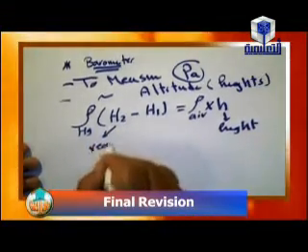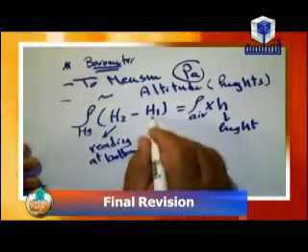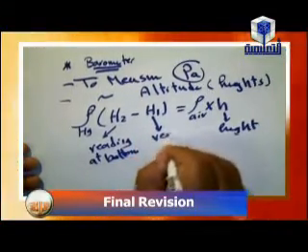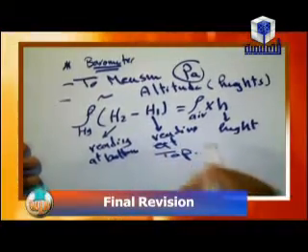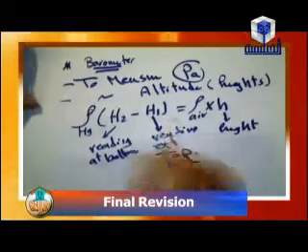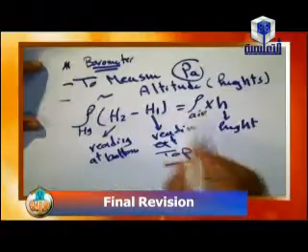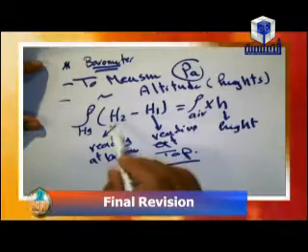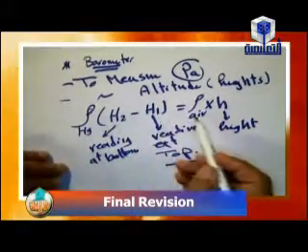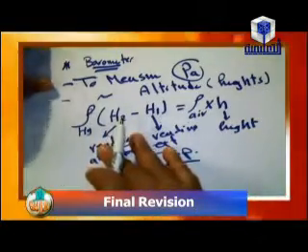H2 reading at the bottom of the mountain, for example, and H1 reading at the top. In any problem, you need to find one thing from this law: rho mercury times (H2 minus H1) equals rho air times H. We can find the height, or rho air, or the reading at the top or bottom, or rho of mercury.